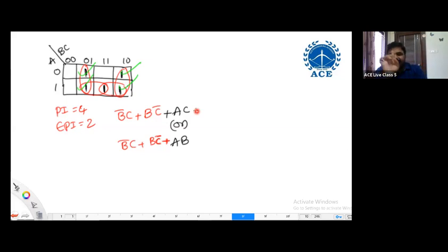So, using non-essentials to cover minterms not covered by essentials, we are observing multiple ways with the same minimum complexity. That is the reason there is no priority on which one to choose. Then you can consider any one of these. When we get such situations, we can have multiple minimal expressions, when trying to cover minterms which are not covered by essential prime implicants.